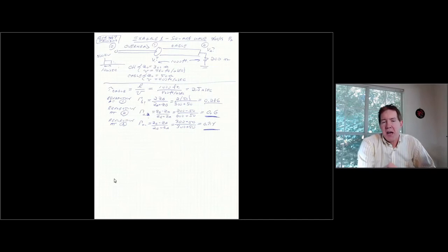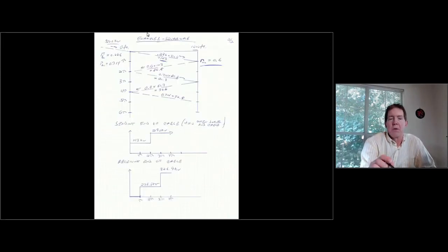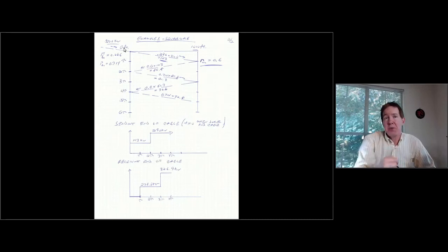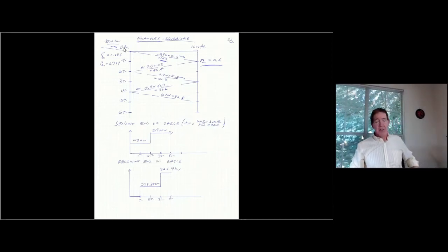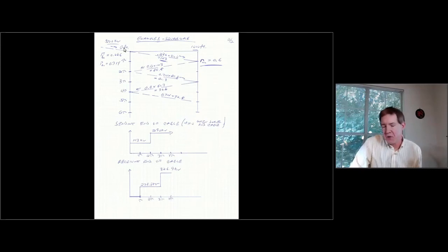But one way you could model something like that would be to do the pulse bounce diagram assuming a 500 kV source, then after 10 microseconds you add a minus 500 kV source. You use superposition. That's a trick you could use if you're working this by hand. But typically I won't make this too complicated for you. I usually just have you run this out to 1, 2, possibly 3 tau. Otherwise it starts to get pretty complex. So anyway, this is just a simple example to start with.